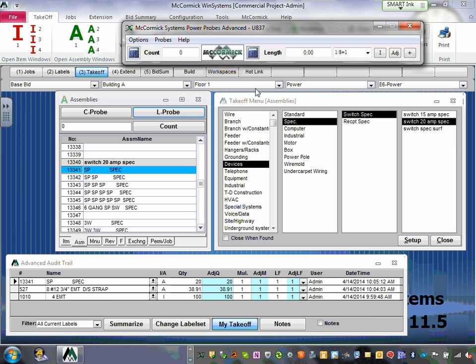Count how many circuits you have. Draw the conduits. Remember, the conduits are going all the way to the panel. So you're going to draw 3/4 inch conduit from the panel to location right into these offices right there. Pick how many circuits. Up to 8 circuits, you can pick them 3/4 inch. In the walls, move through the cable. When you take them up in the ceiling, move them through a conduit.